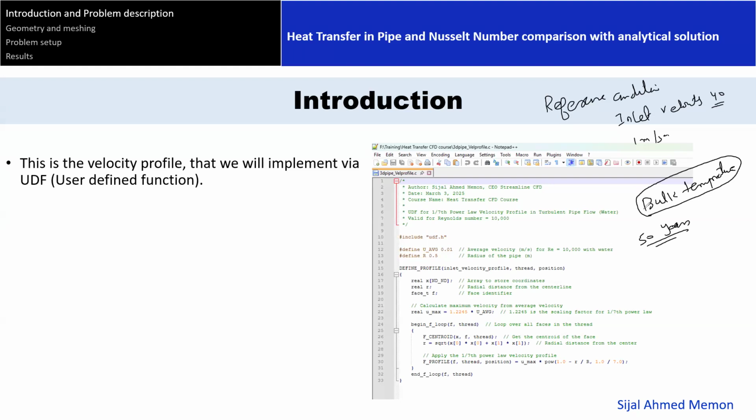Now everybody can go to some CAD software, design, use SpaceClaim to clean the geometry, create the domain and boundary conditions, then quickly create the mesh in Ansys meshing. Not a very good mesh, but it's still a mesh, and then he can run the simulation. He knows from the sources that he needs a certain y plus. Even without knowing more, they know y plus should be one.